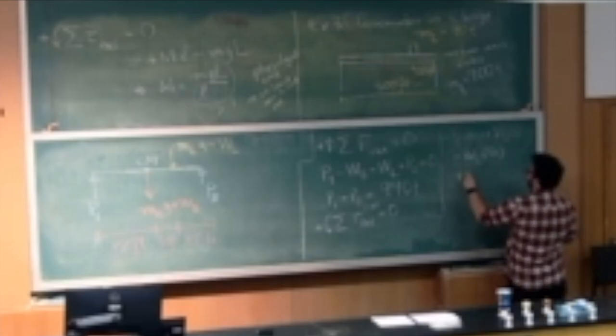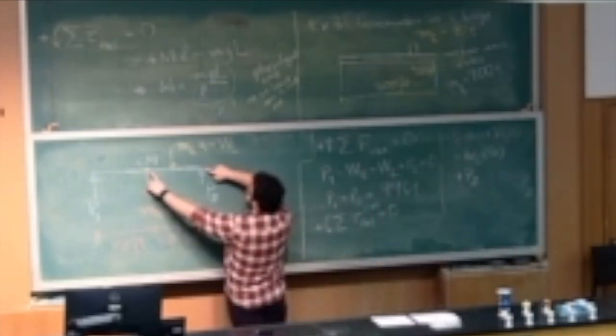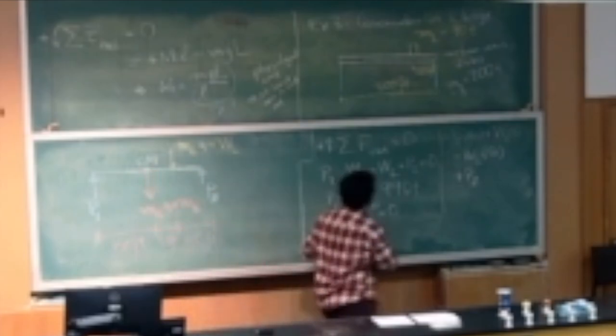And now we have the last one, P2, that is trying to rotate my bridge, my object, in the counterclockwise direction, so it is trying to create a positive torque. P2 times the moment arm, which is right here, 150. This must be equal to 0.